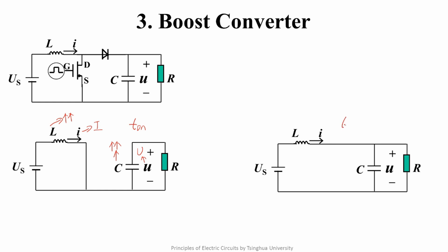is T off. If the current enters into the steady state, then for the energy storage element inductor, the energy stored during T on is equal to the energy released during T off. Okay, we calculate it now. If you want to calculate the stored energy during T on, it needs to set such a reference direction for the inductor.